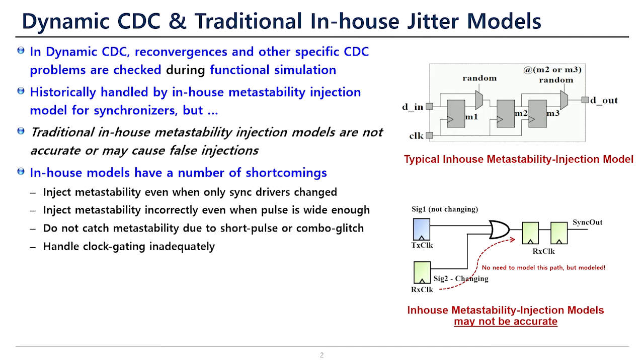Typically, the upper right side of the schematic shows the traditional synchronizer jitter model. There is in-module modeling of the metastability of the first flop of the synchronizer. Designers typically use this model to model metastability and to check for any metastability problem.